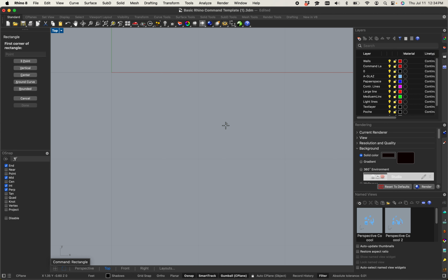So I'm just going to draw one by memory, and I want to draw it to an actual scale. One of the main rules of drawing anything in a digital realm is that you make it 1-to-1. If the building actually is 25 feet by 25 feet, you type in 25 by 25 feet. The reason is that in the digital world, we want the model to be 1-to-1 scale.